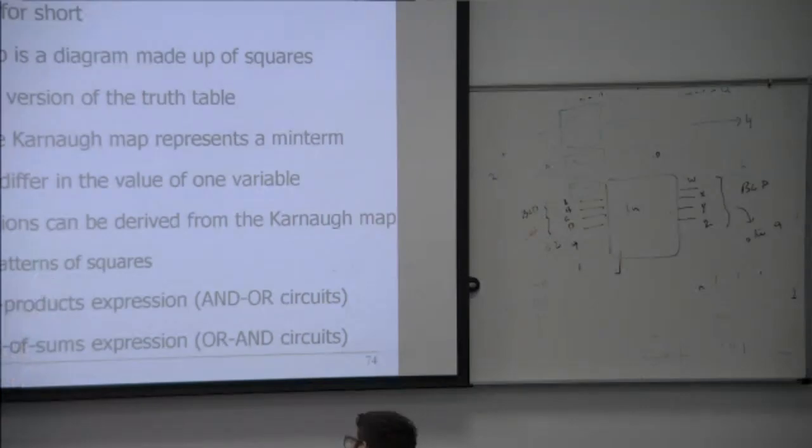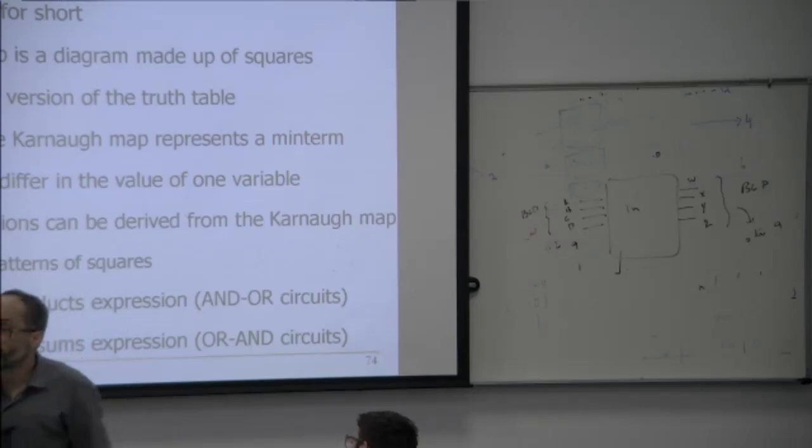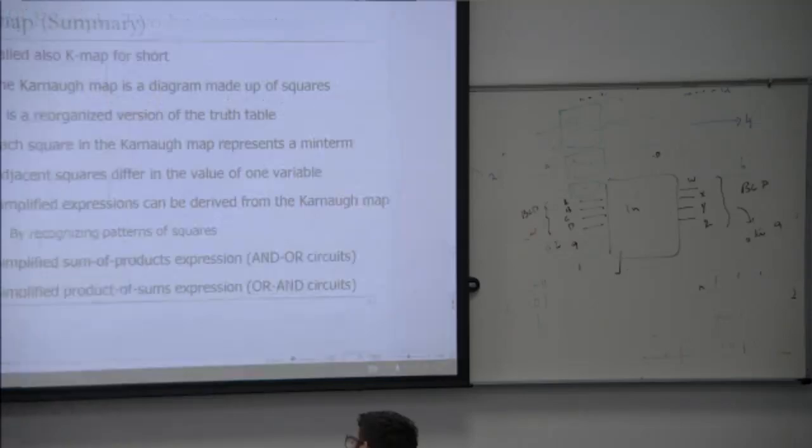Should we proceed? If you have any function, we will draw the truth table. From that truth table, we do the minimization, then we identify the shared terms, and then we use the shared terms to further reduce the cost. This is called a multi-objective optimization problem.